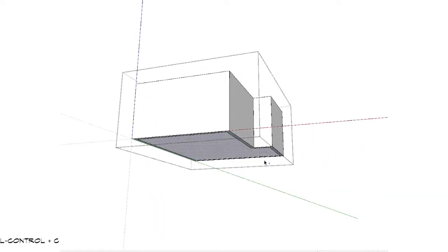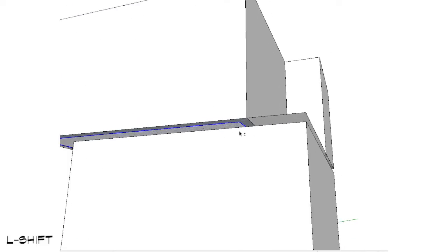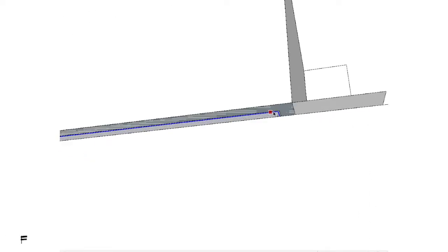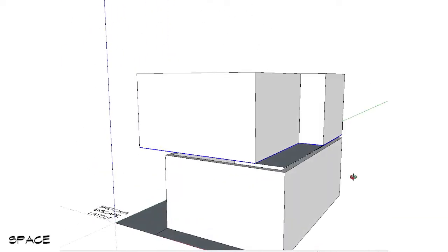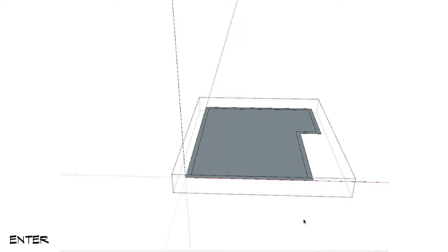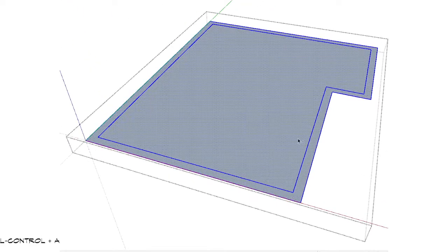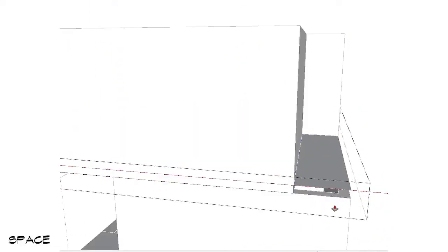Okay, copy that. I paste it outside in place, or using File, Edit, Paste in place. Then make it bigger. Select the whole thing. Press G to group so I could see what I am working on. Just press enter to go inside. Let's say for example the whole thing is a slab, so I don't need those interior lines. I could just make it a slab.